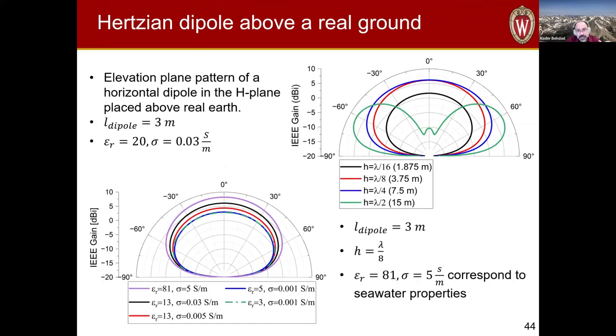Now, our real Earth is not a perfect electric conductor. So if you want to figure out exactly what happens with your antenna, you have to do that modeling, using, for example, software like NEC or FEKO to do this analysis. The general trends are still the same: you'll have some image currents that would be oppositely directed to your main radiation. But let's see what happens here.